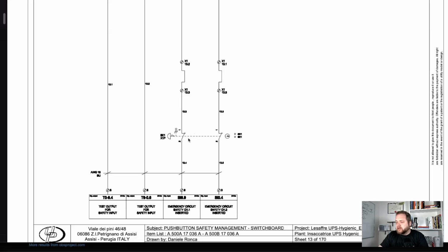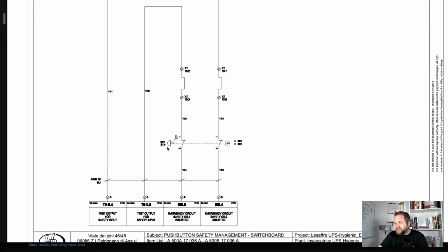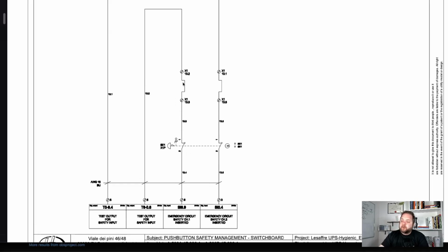So basically we have a push safety stop, and you will notice a couple of things here immediately, right? As I look at this safety circuit, it looks like they have 2 sets of contacts that are short-circuited with this little bracket in between them, and for me that indicates that this machine can be tied into something else once it comes onto the plant.